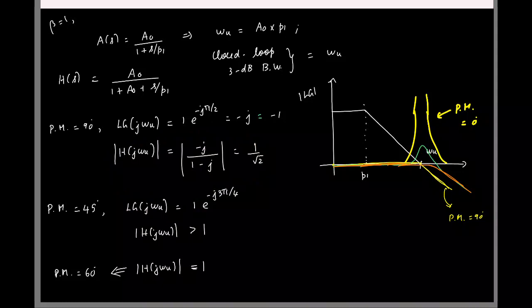Beta equals to 1. Beta equal to 1, yeah. It doesn't matter what beta is. So that's why for practical systems you try to keep the phase margin to be greater than 60. That way even the closed loop response doesn't show a lot of peaking.